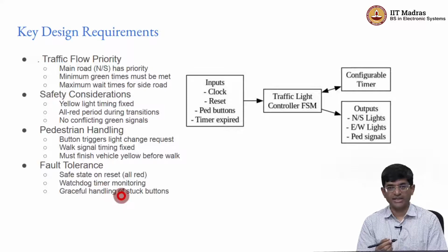Watchdog timers, these are critical safety components over here, right, because traffic light control actually has life or death consequences if not implemented properly. You need to make sure that the system does not get stuck in arbitrary states. So, watchdog timers, things that basically just make sure that your system is transitioning out of any stuck states, are required in general in these things.